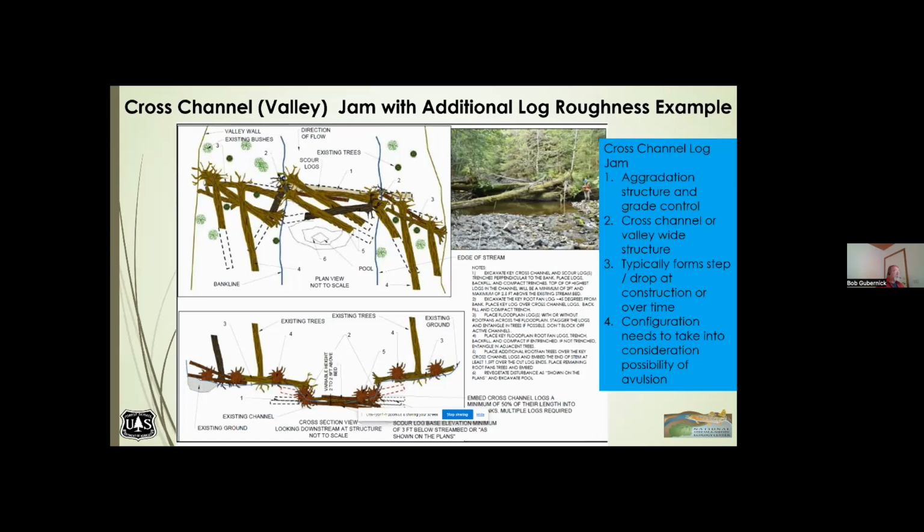In time, they can plug up and backfill. Most of the time, they fill up with sediment. They capture some sticks. There's places on there that are still porous, but it's accumulating material up above because it really slows velocity and changes the hydraulic gradient of the water surface, and essentially it drops its load back there.